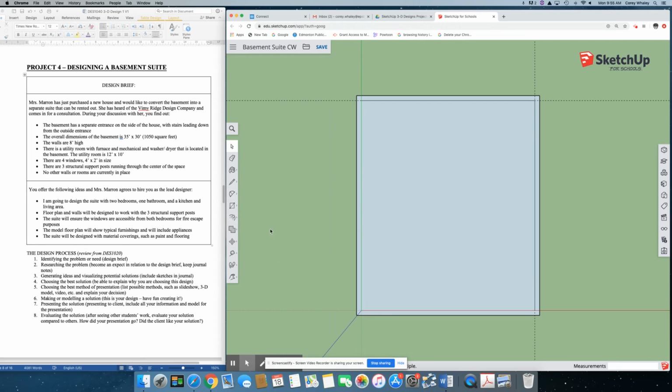Okay, so we're going to continue and just put down some guides, so we can sketch out how the floor plan is going to look before we actually start building things in there. With those guidelines, you can leave them in and delete them later. The way that you delete them is just grabbing the eraser tool. Actually, these exterior ones we no longer need. So I'll grab the eraser tool right now, and you just click on the line to get rid of those guides.